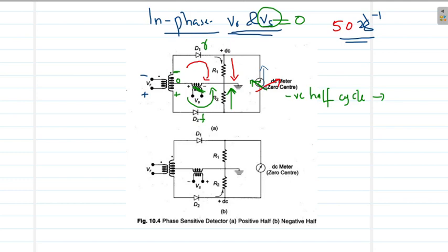So if something is oscillating at a very high rate to left and right, it will not be able to execute both these motions, and apparently it will stay fixed at this mean point. So what you will observe on this galvanometer is a null deflection, because of this balancing of positive half cycles and negative half cycles, which are repeated many times during 1 cycle. So this is the situation when Vs is equal to 0. We have null deflection on the galvanometer.